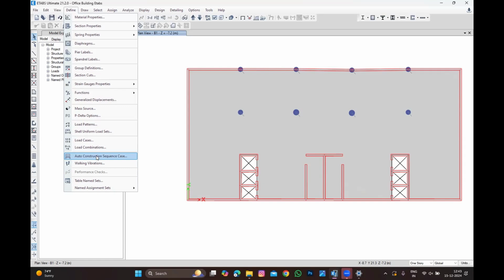We have a lot of things to cover. Don't go into non-linear now itself. Non-linear is the one which you cannot predict. If you want the best example, take how you do a chain survey in roads. If it is 10 kilometers and the bare ground has so many undulations, as long as you don't take close readings, you will never get the actual undulation, and then you will never calculate the cut and fill. Why do you do the chain survey? To calculate the cut and fill in the road: how much is the cut quantity, how much is the filling quantity.